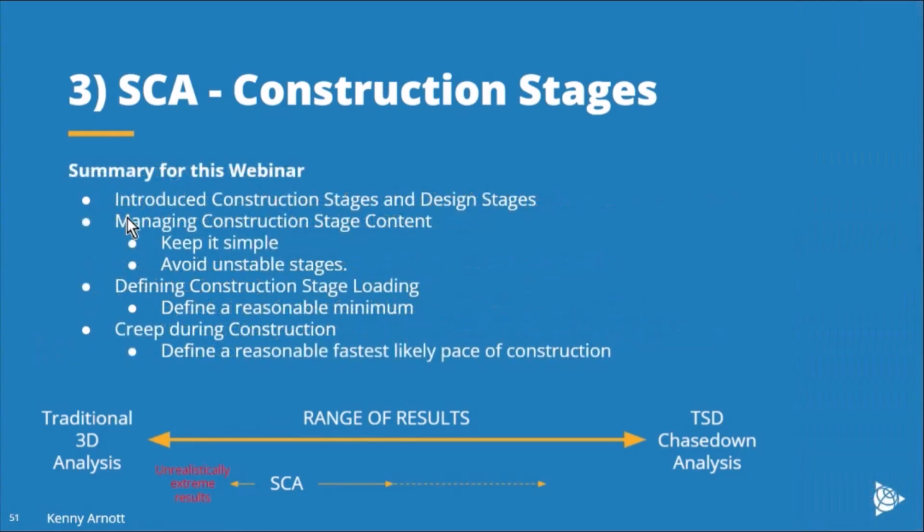So an overall summary for this webinar: I've introduced the construction stages and this concept of separation of construction and design stages. Talked about managing the construction stage content, keeping it simple, to try and think, as I say, in terms of what's happening month by month rather than day by day, and keep an eye on avoiding unstable stages. When you're defining the construction stage loading, you could be thinking what might it be, but as long as you define a reasonable minimum, then you start to move the stage construction analysis results away from the traditional 3D results.